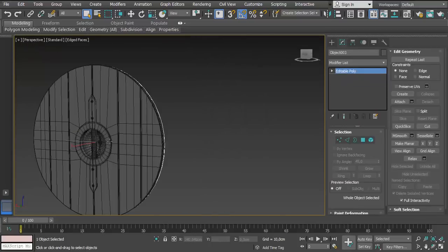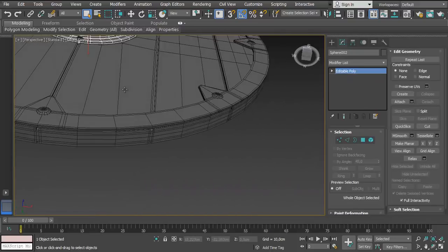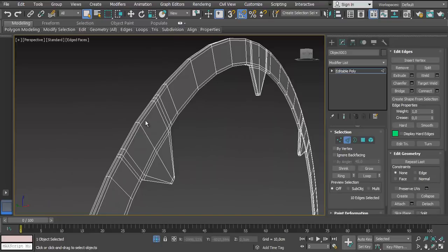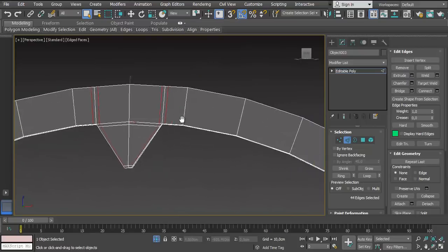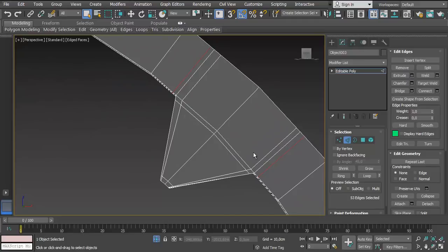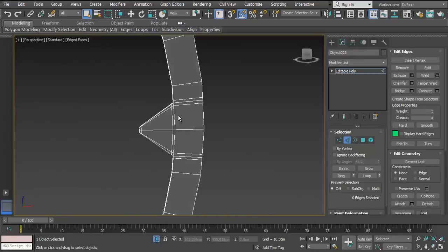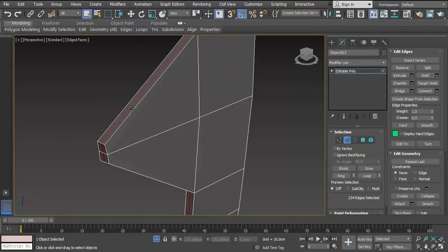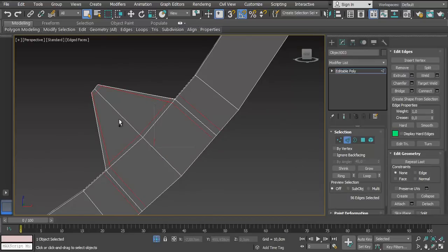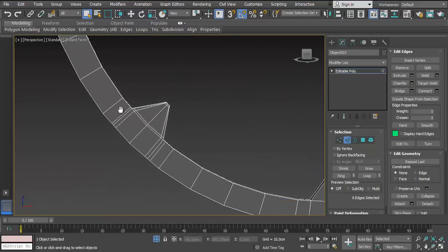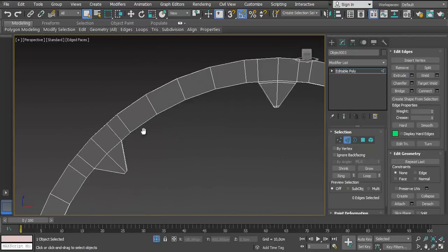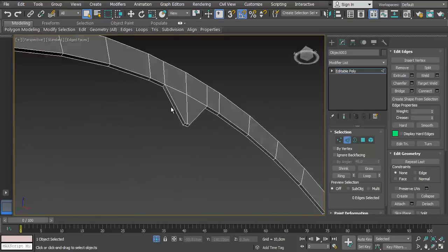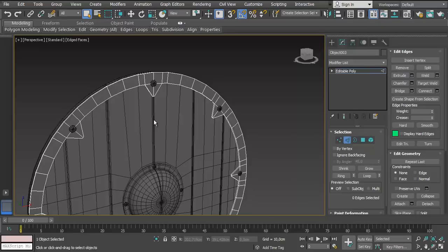We're going to remove everything that is floating on top, especially the pins, bolts and screws and anything that is small pieces on the surfaces, extruded areas like bumps, and anything that is carved in surfaces, especially if it is small or has a large quantity of details. The shape of it is going to be difficult to create on the high poly, and the cost when it comes to the poly count is going to be super high, and this is a very strong indicator that you need to cut it out and not leave it in the low poly.